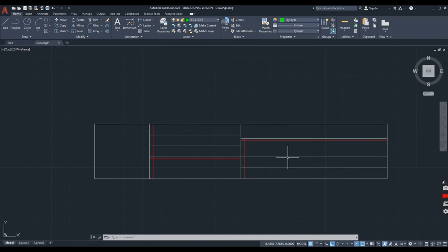Okay, an eighth of an inch is our default size of any text that we do on a drawing. Though I'm going to have a bigger piece of text up here, okay, for the Camden County College, and that's going to be 0.1875 or 0.187. And then I have a smaller text over here that is 0.075 for our tolerance block.